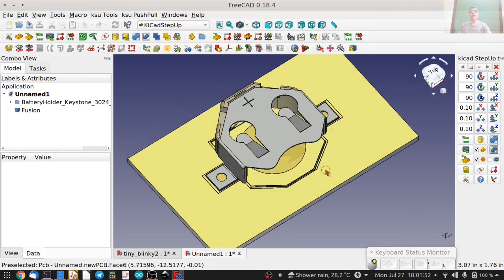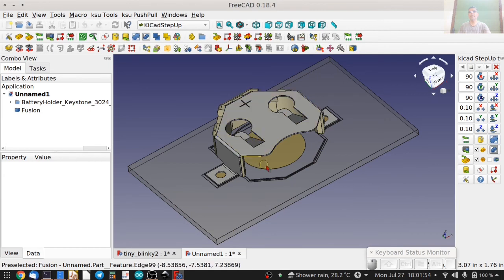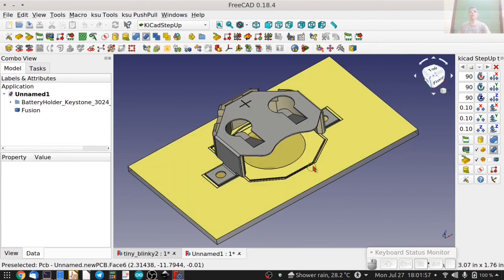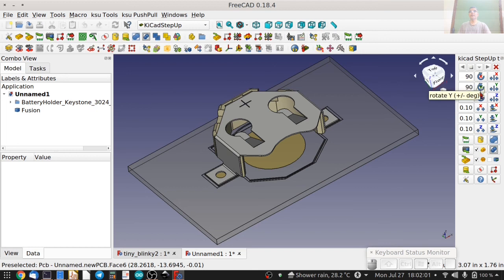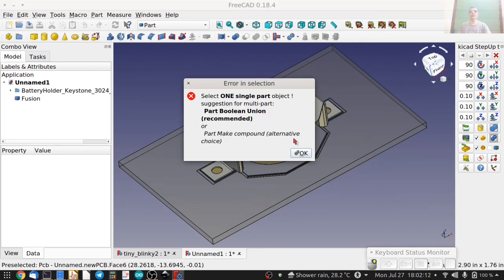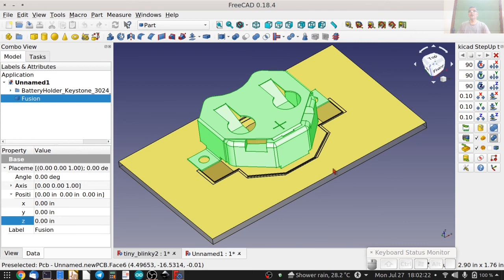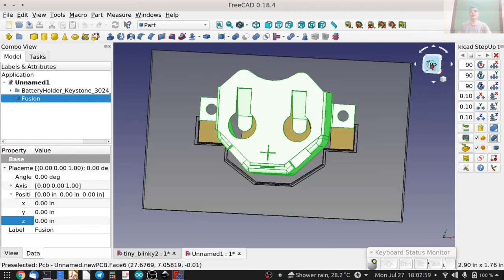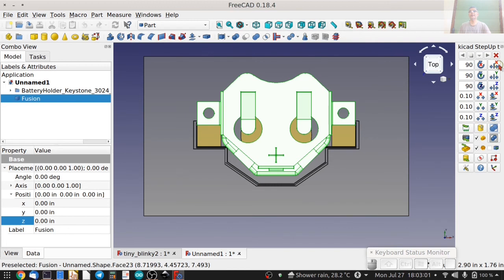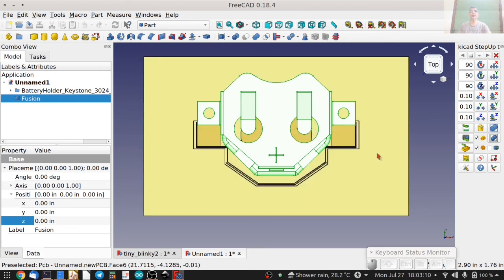It needs to be rotated 180 degrees along the Z axis. So that is pretty easy. You have these three rotation options over here. Rotate along X, Y, and Z. And you can choose the angle over here. We'll have to select the object first, which is this one. Then rotate twice along the Z axis. Let's look at the top view and make sure that it is centered along the X axis by using this icon, Center X. So that fixes the centering on the X axis.